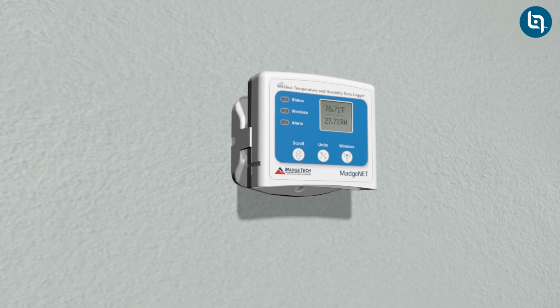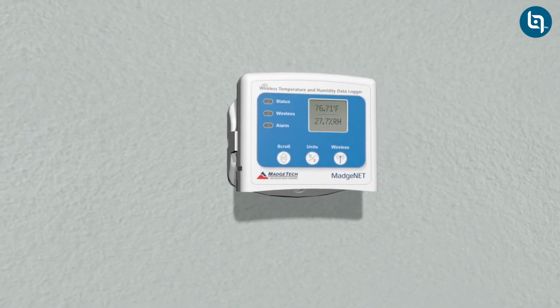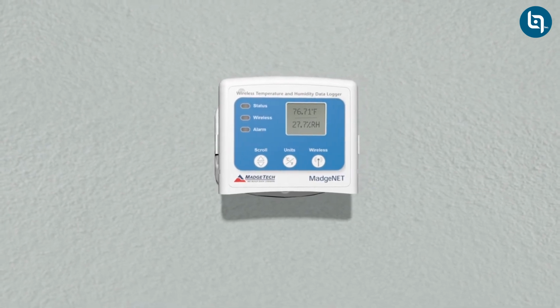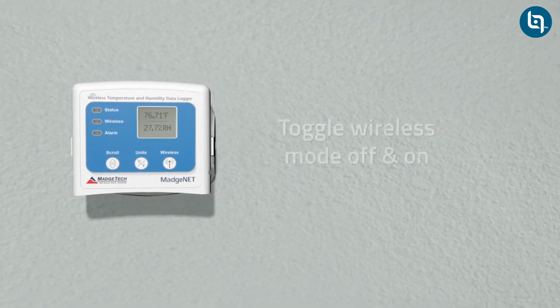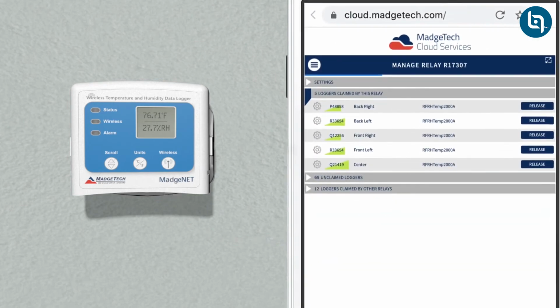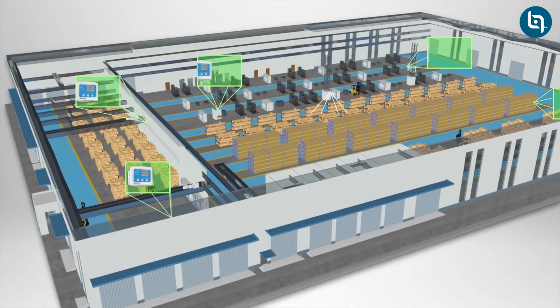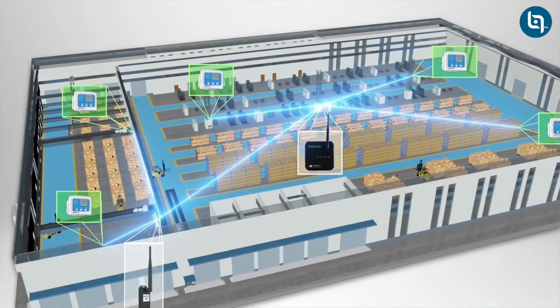Once transceivers have been placed, we now need to ensure the loggers are communicating with them. A logger will only connect to a new RFC 1000 or cloud relay after losing connection. If new repeaters or relays have been added to the network, turn off wireless mode on your data logger. Wait 30 seconds, and then turn it back on. The logger should now connect to the new repeater or relay with the best signal. To confirm efforts were successful, reference the MadgeTech Cloud web application once more and view the signal strength indicator shortly after toggling wireless mode back on. Depending on the size and construction of the facility, more transceivers may be needed to achieve best results.